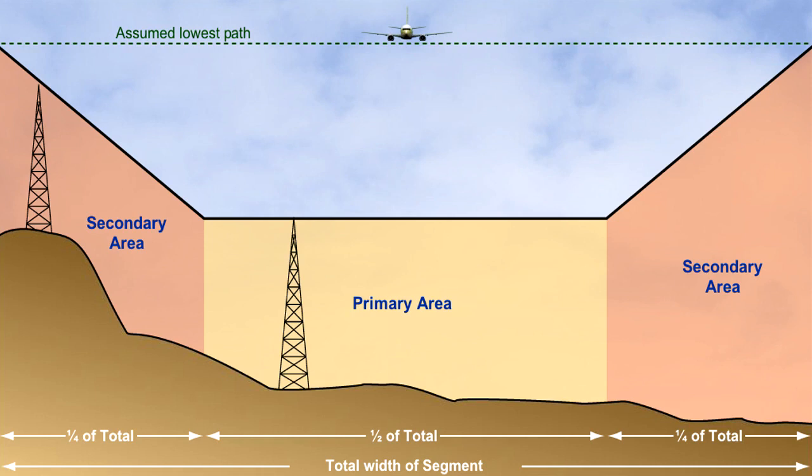Here is a vertical cross-section. You can see that, in the primary areas of the footprint, the full obstruction clearance must be guaranteed. However, MOC reduces to zero as we move away from the primary areas through the secondary areas. If there is a particularly troublesome obstacle, then of course the departure track can be adjusted until the obstacle is overflown by a secondary area at a height that clears it sufficiently. This ends our discussion on minimum obstacle clearance during departure procedures.